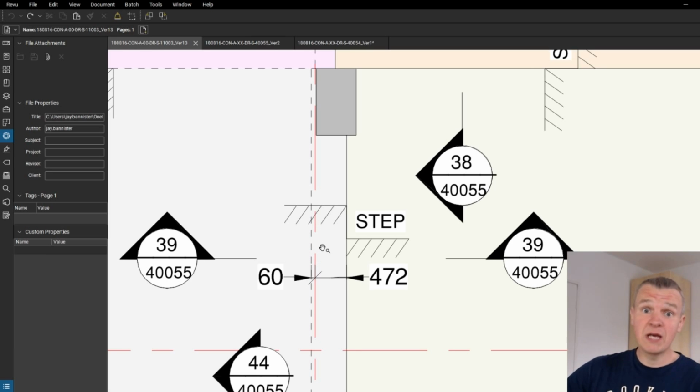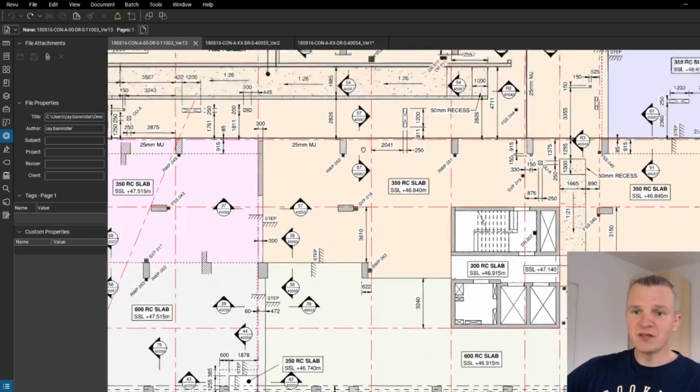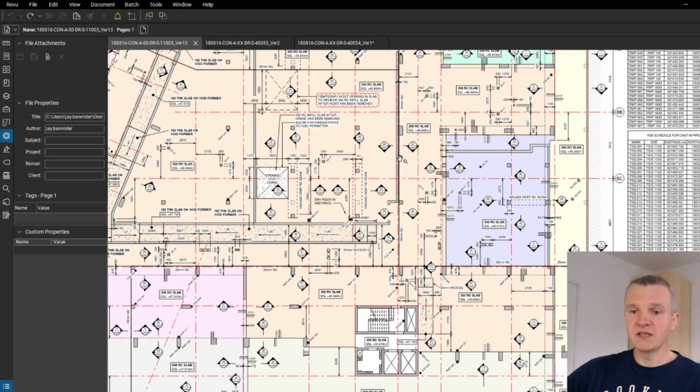And this is very important, guys, because once you're going to do the setting out and once you're going to start doing the decking, which you actually can see in one of my videos, you need to have a look at these lines, as these are the lines actually to be marked and to be shown, guys, before they start doing the decking, and you need to keep an eye on these things. So that will be the very important information to take from the drawing as one of the first things. So we've got the levels, we've got all the sections here actually. So that's the next information.